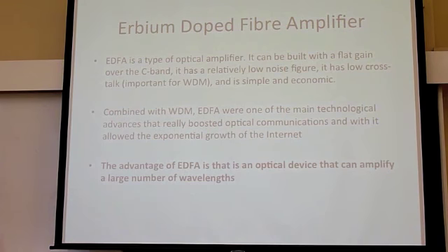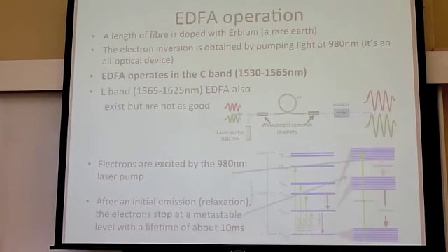Combined with WDM, this EDFA is actually the main technological advance which has led all telecommunication advance. It means you can put a lot of channels together in the same fiber without using another fiber. And with the same amplifier, which is slightly more expensive, you can amplify all the signals that go through. So that was a big advantage. Again, the big advantage is that it's optical and it amplifies all the wavelengths that go through it, so no need for an amplifier for each channel.